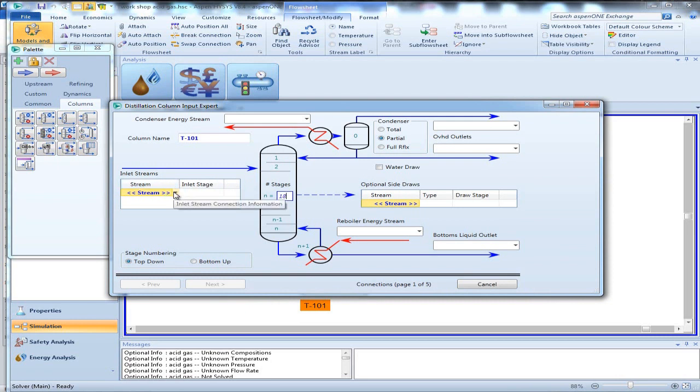The gas that comes out is, of course, the lean amine to purify, and this would be full reflux. So only the gas product will come out. So I put that at the QC, of course, and QR for the reboiler energy use.